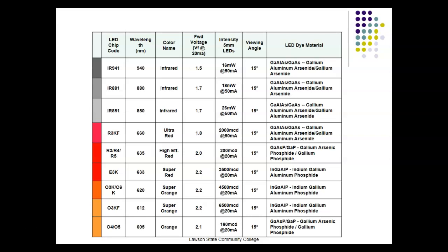And this tells you exactly what they're doped with. You need to know this? No. All you need to understand, number one, is that they're not silicon and they're not germanium, and the VF is going to be greater than 0.7 of a volt because you've got to create more energy to cause those photons to come out, right? That makes sense?